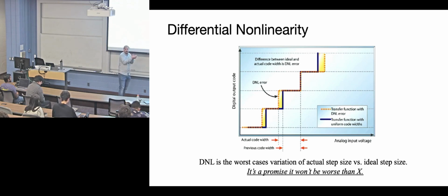But there could be manufacturing errors which cause them to be different. You as a user or a designer, the only way you could figure that out is if you go and calibrate every ADC or DAC digital value and measure it out. And so that's probably impractical, especially if it's a high number of binary values.